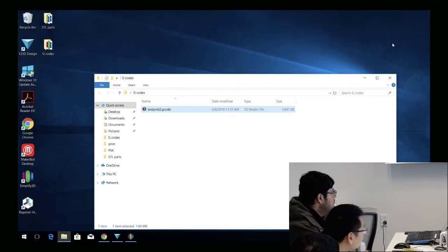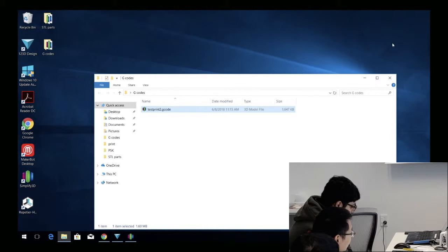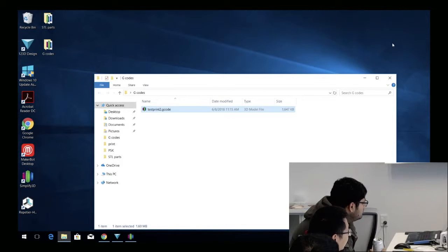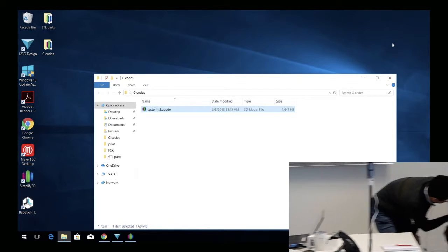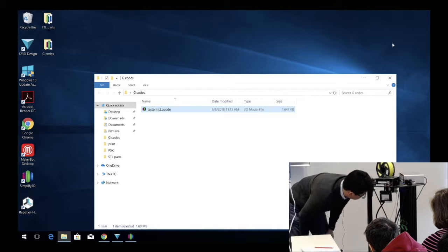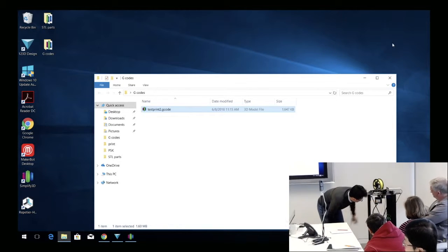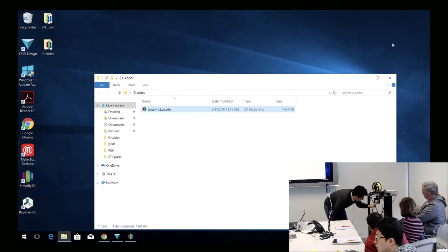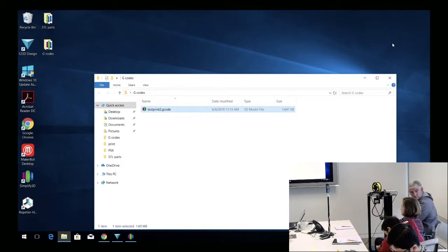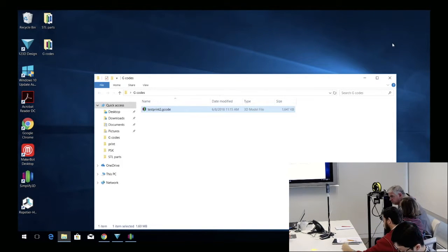So I think all the steps are actually described with screenshots in the profile. You just choose a profile and do the printing. You see on the right side is the heat bed temperature. It will reach 60. Currently it's 23. And on the left is the nozzle temperature that will reach almost 200. This is the time that has been consumed. This is the progress percentage. And if you run into any trouble and you want to cancel, just do the operation on the right side and click stop. That's it. And also, this is written in the manual. Yes, yeah. We'll see how it looks like.